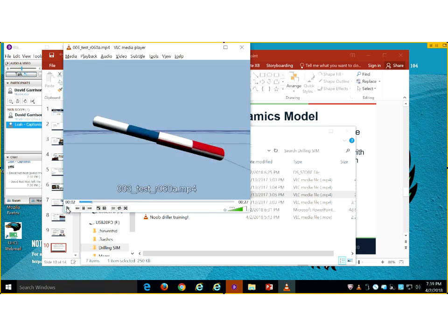And so for a driller, the operation of connecting two pipes together is of critical importance. And so we spent a lot of time trying to figure out how to accurately model the physics involved in screwing two pipes together. So you have the pin on one pipe and the box of another, and if you slam them together, then there's going to be a collision. And in order for you to screw those, there has to be basically relative rotation, and the relative translation of those two pipes is sort of constrained by the pitch of the screw.